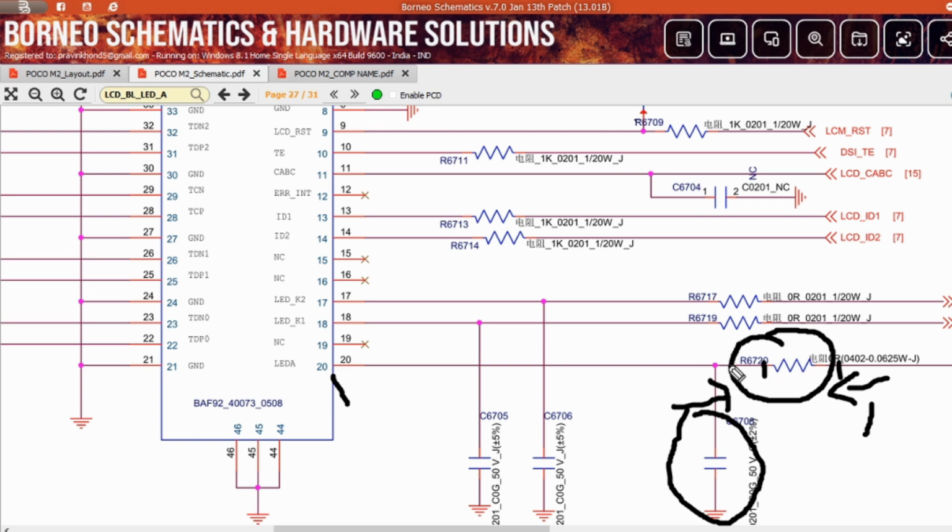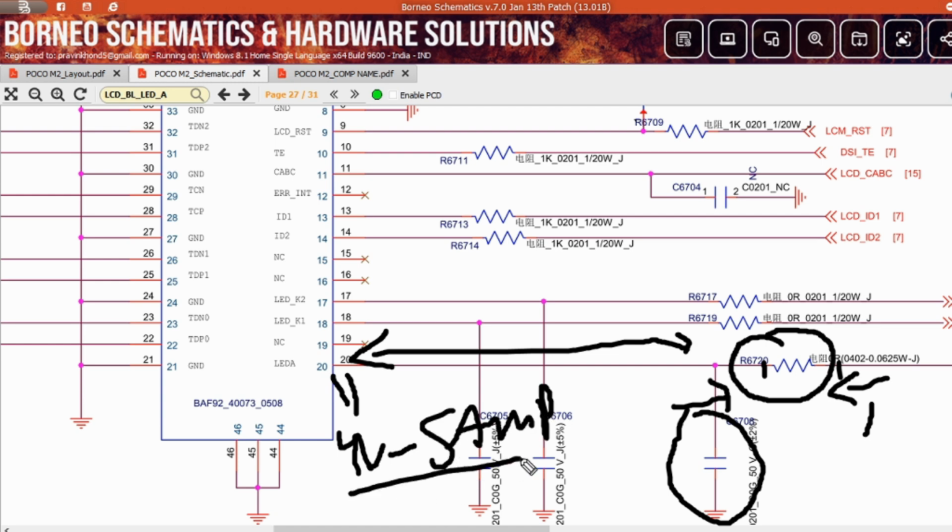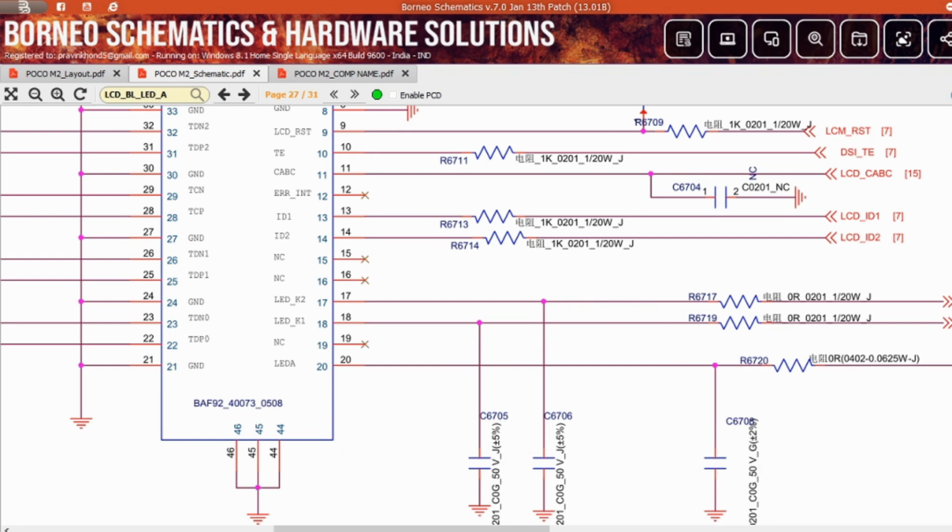If you do not remove this resistance, and only this line had a short, you can apply the rosin method on the light circuit near the light IC, and also on the filter caps in this area, and you can inject voltage here, like 4 volt and 5 amp. There is no shorting on this circuit. Clear? I will explain on a motherboard so you can better understand.